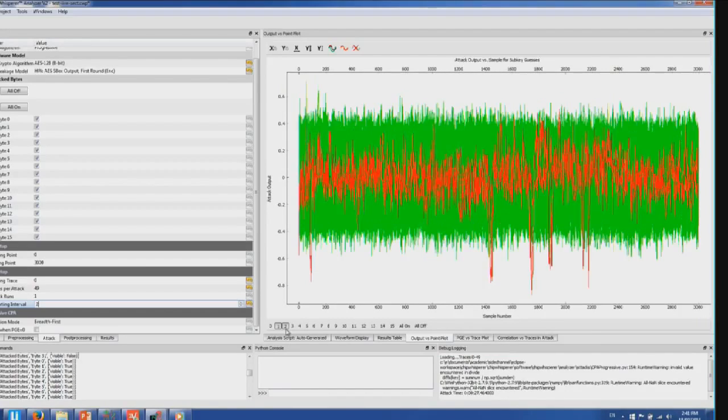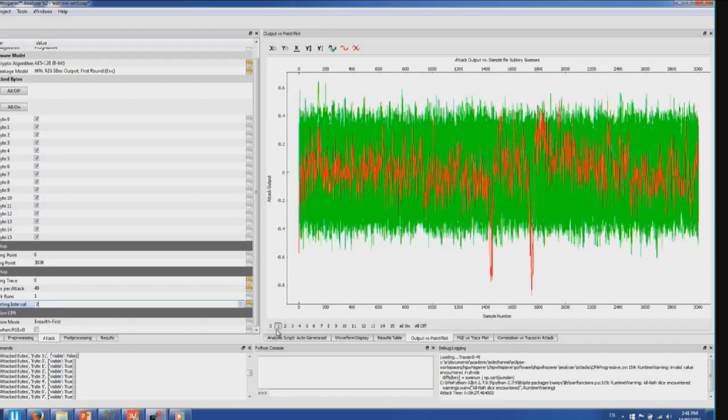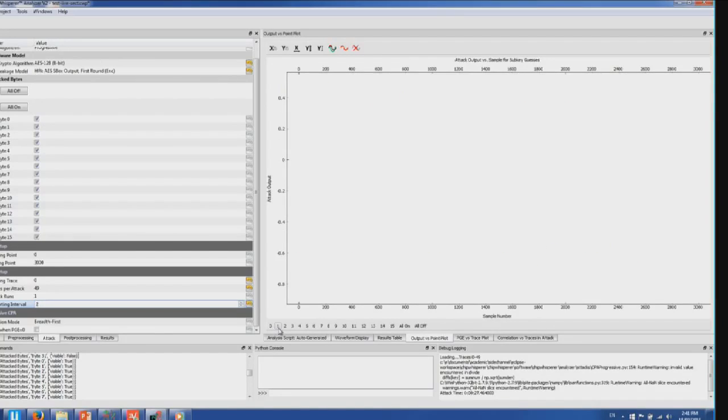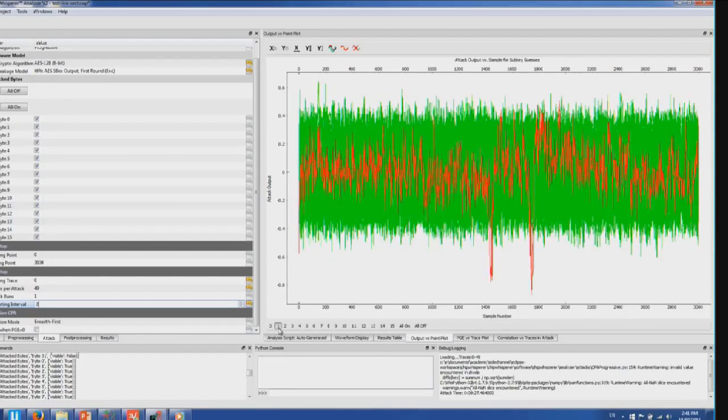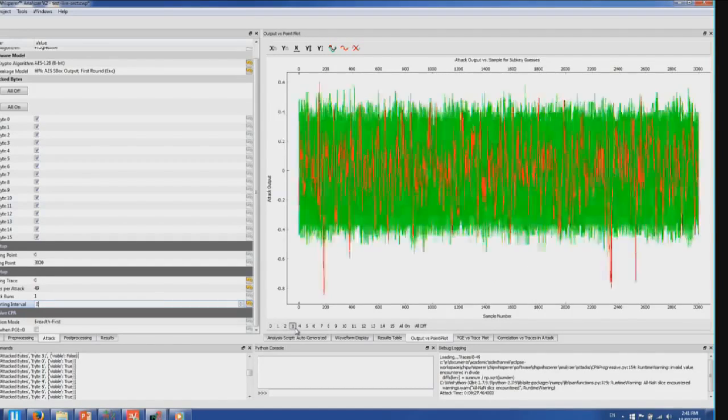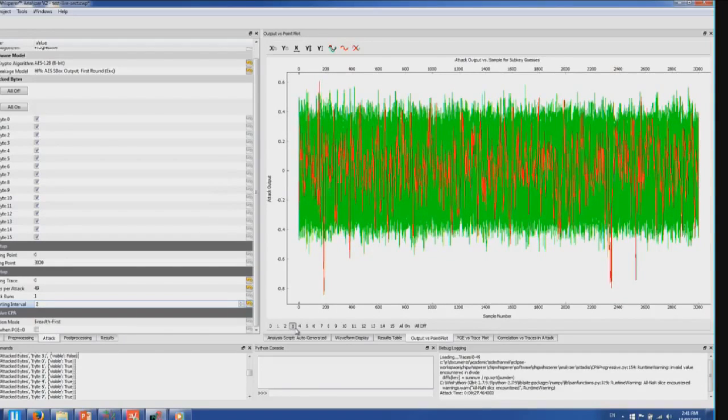The other question people have is how did I know when to look for the power? Because it's doing a whole lot of stuff. The cool thing is that everything that's not the encryption filters away in the algorithm. What I've done here is this is showing you several points in time, it's 3,000 samples. In real life, you would send it the command to say encrypt. In reality, you might send it an authentication command, and you just start recording power until it returns the result.